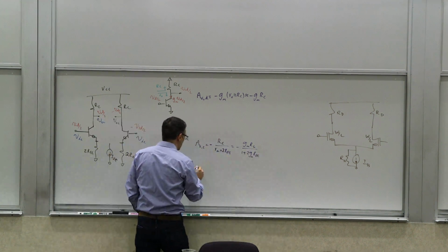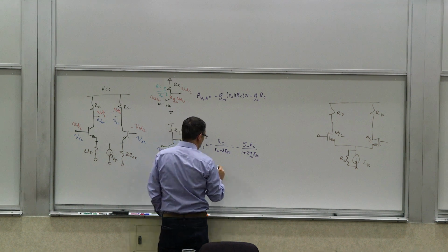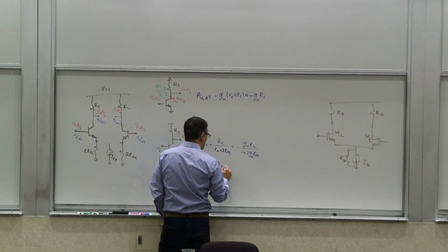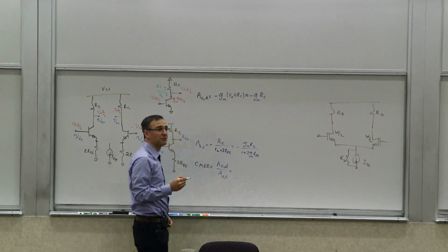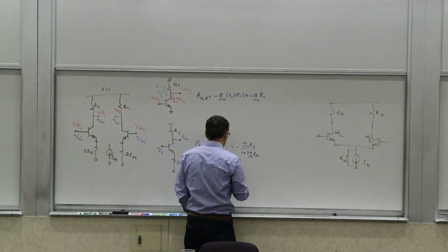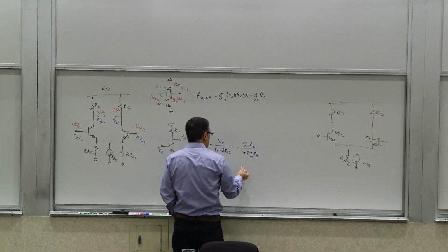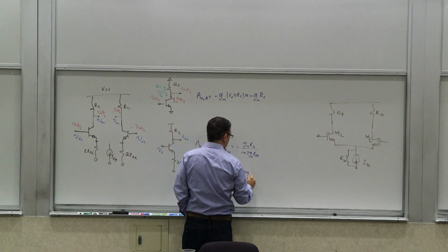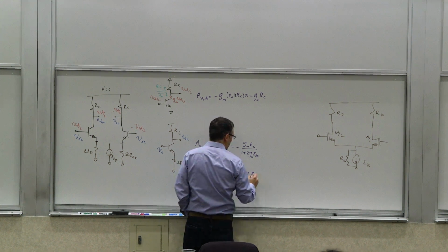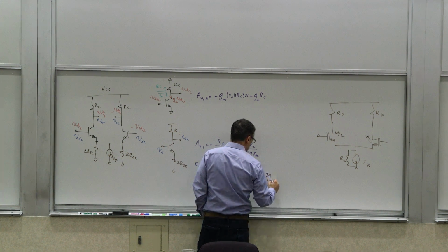And of course, from these two we saw last time, and these are nothing new, the CMRR, the common mode rejection ratio, which is defined as the ratio of the differential gain to the common mode gain. This makes sense: it is the amount of suppression you get, how much you amplify the differential and how much you attenuate the common mode. In this case you will get 2 plus GM REE, 1 plus 2 GM REE, roughly, if REE is large, it's going to be 2 GM REE.